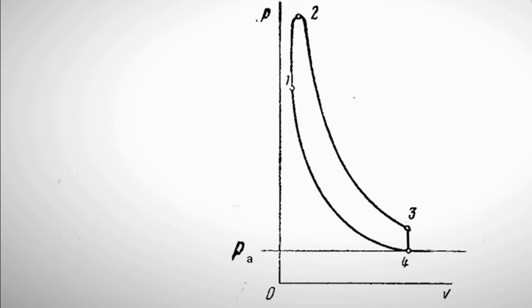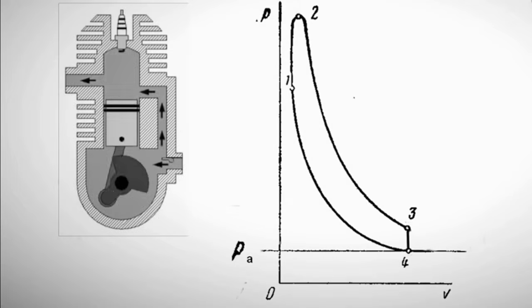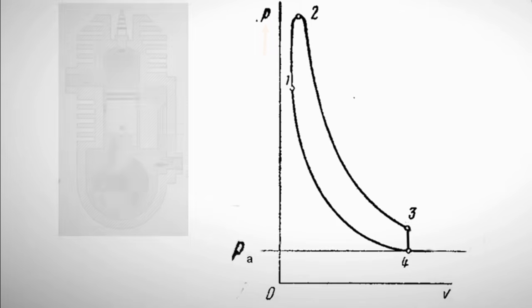A simplified indicator diagram of the compression and expansion strokes of an internal combustion engine will explain the essence of what is happening. As we know, an indicator diagram records how the gas pressure in the engine cylinder changes at different stages of the piston stroke, that is, as the cylinder volume changes. The vertical y-axis of this chart represents the cylinder pressure, and the horizontal x-axis represents its volume.